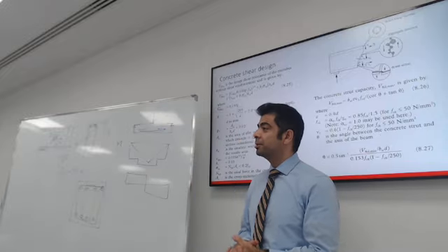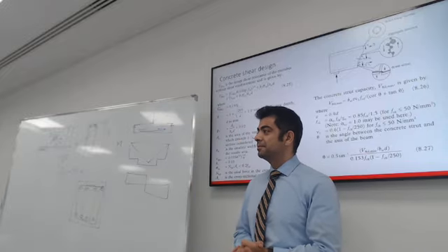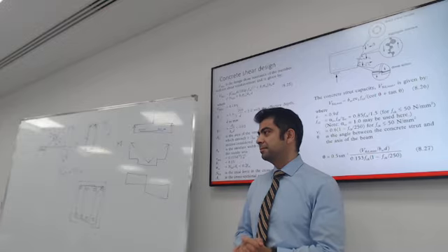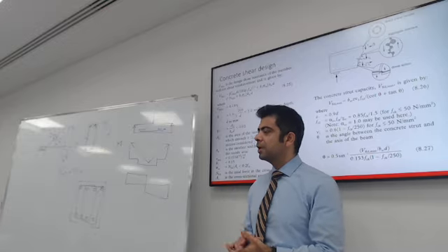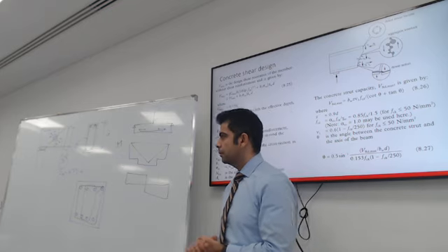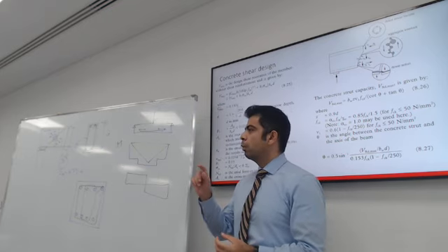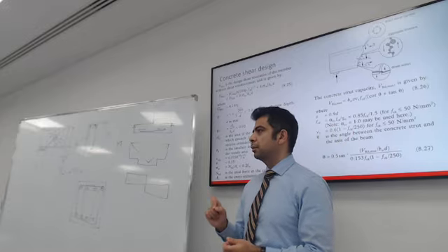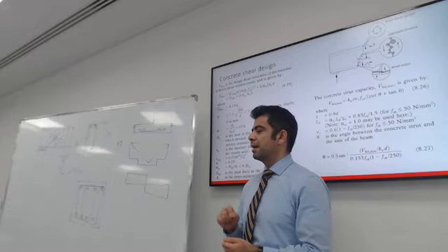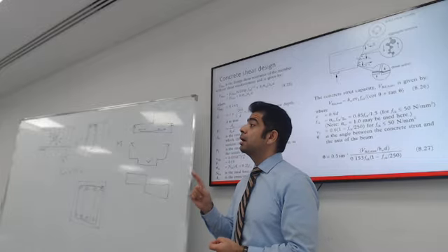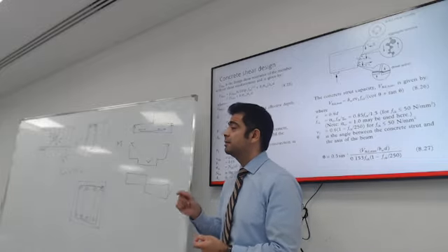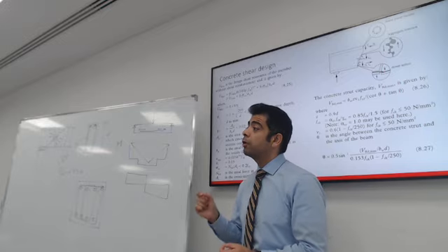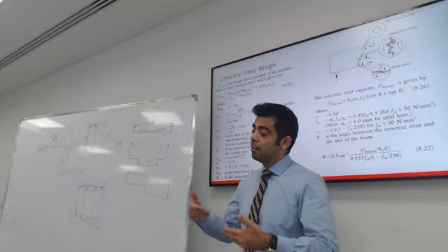Do you have a question? Tension is going to increase a bit in the bottom and it's going to result in either extending the length of the steel bar or adding more steel. Okay, we will always extend the bar. This will always happen. We will always extend the bar, and sometimes it might not be enough and we need to add more reinforcement. So not all the time will we add bottom reinforcement.